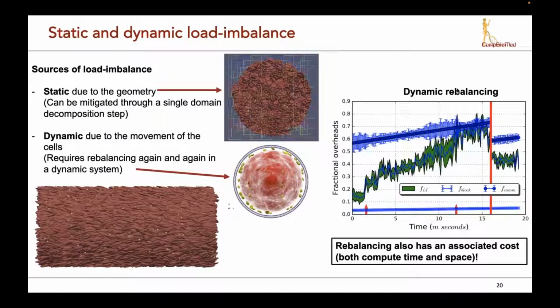Another typical problem that will arise in every single simulation, not just blood flows, but everywhere where we have coupled components that move compared to each other, is the appearance of load imbalance. Static load imbalance is something that has long been known. There is a demonstration in the top figure where you can see a cylindrical vessel flow and the domain decomposition. And what you can notice is there are colorful blocks at the corners, which are basically empty. This is just a regular decomposition, the most naive one possible, but it leads to load imbalance because there are blocks assigned to CPUs that are not doing anything since those blocks are empty.